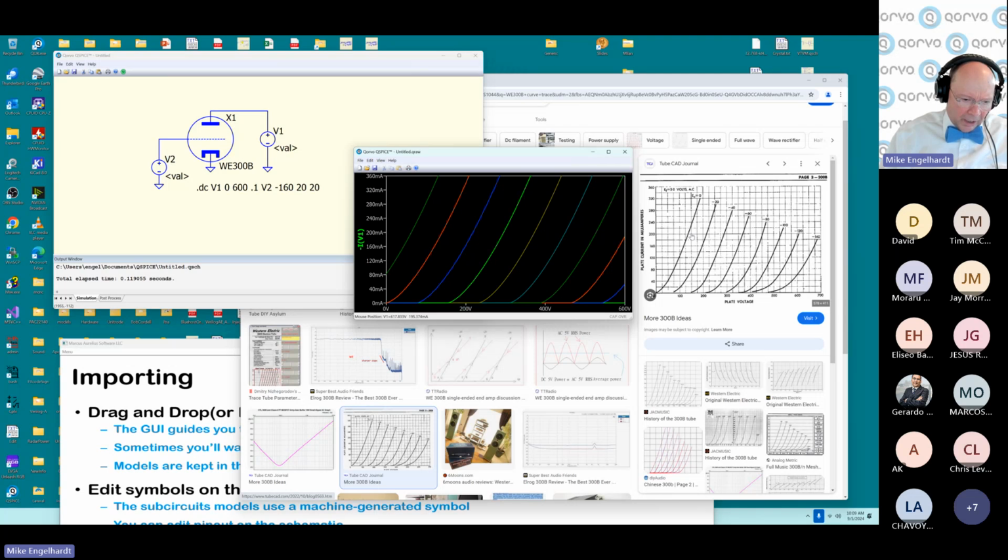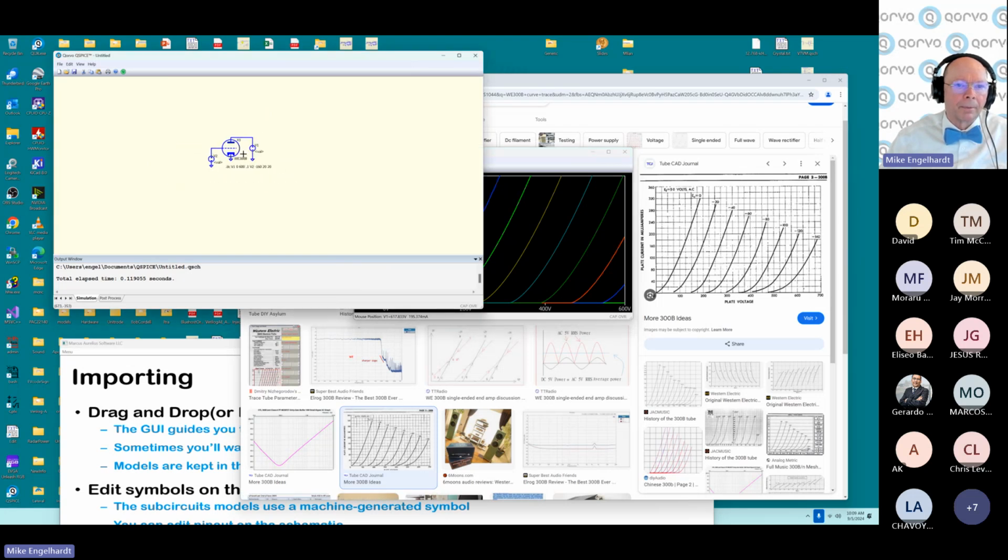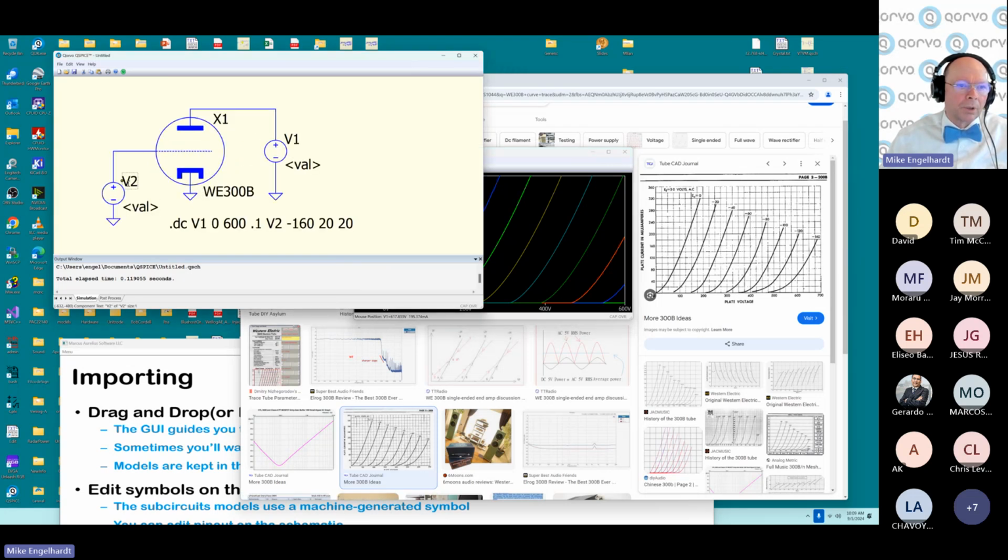Everything in the schematic is an integer. It's rendered to floating point, so I have a nice floating point zoom here. But the actual data objects are stored as integers, so everything is on a grid all of the time. There's absolutely nothing you can do about it. You cannot store information that's not on a grid. It's always on a grid.